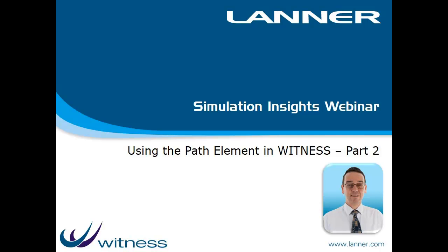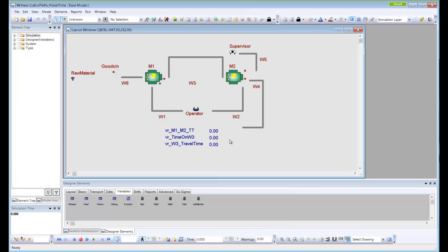around, and it is using paths. And in the previous example I showed the way we use the walk time function to allow the time along the path to vary depending upon the length of the path, which can be very convenient, especially if you're stretching your paths to lay them out on top of a CAD background. However, there are times when it is safer for us to set the travel time along paths explicitly, either in Witness itself or more likely from Excel.